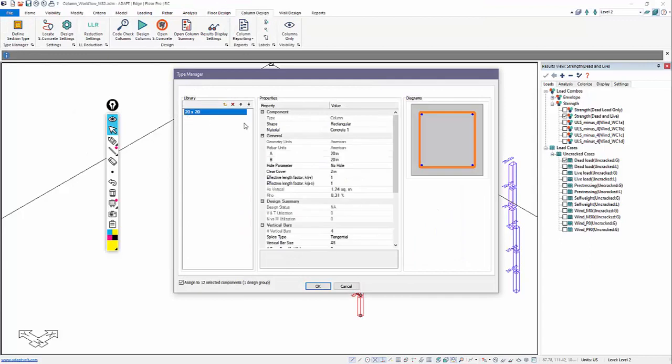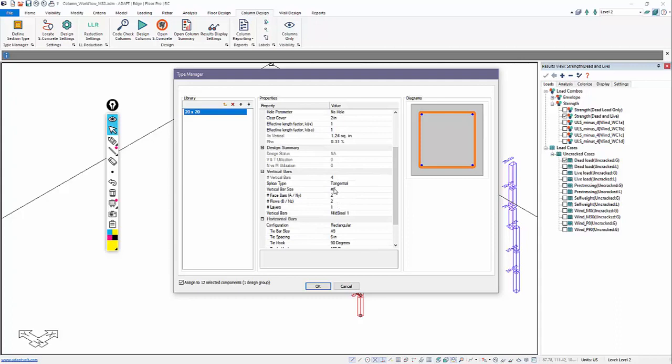So for this 20 by 20 group, we can assign the reinforcement necessary to produce a code check. So we need to start with something. We need to have a section with reinforcement assigned to columns, and at that point the program can then produce a design, which is a suggested design that is set to take care of the different forces acting on the columns, or we can code check and just determine interaction ratios based on the actions versus the capacity relative to this section.